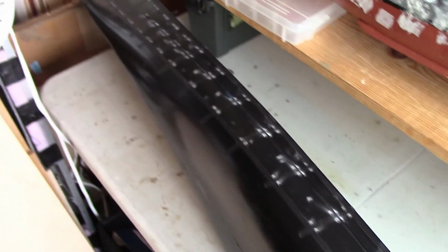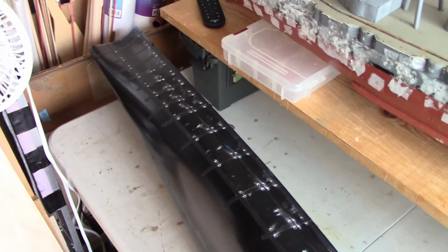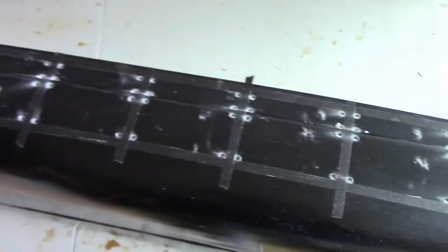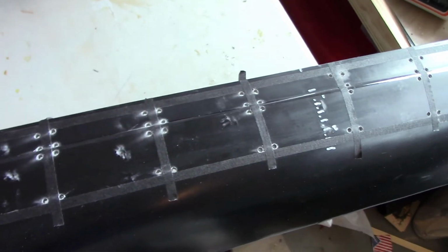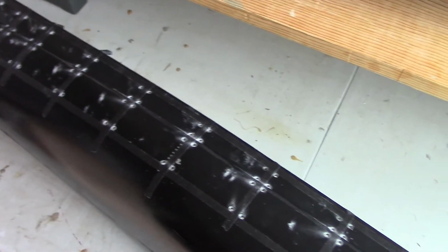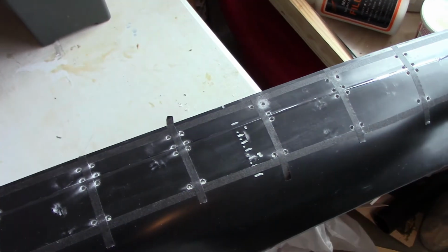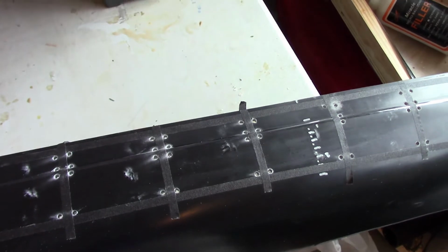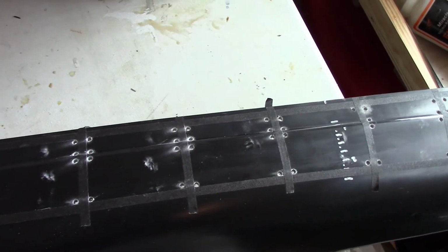The way I'm going to approach this is I'm going to cut all of the same edge moving down the hull at the same time. For instance, I'll cut all the bottom cuts first and go down the whole length of the hull, and then I'll cut one side of the rib and go all the way down the length of the hull, and so on. I found that's the most efficient, because you end up holding the tool at the same angle and just sliding the hull down as you go.